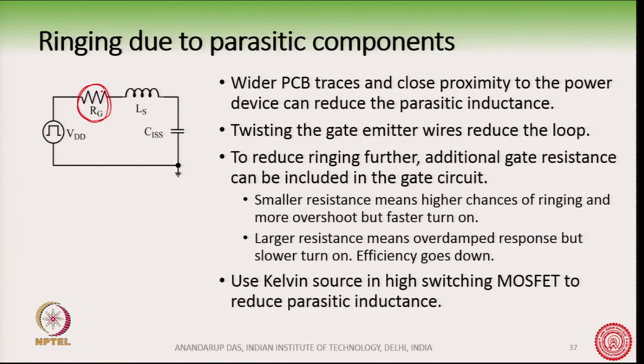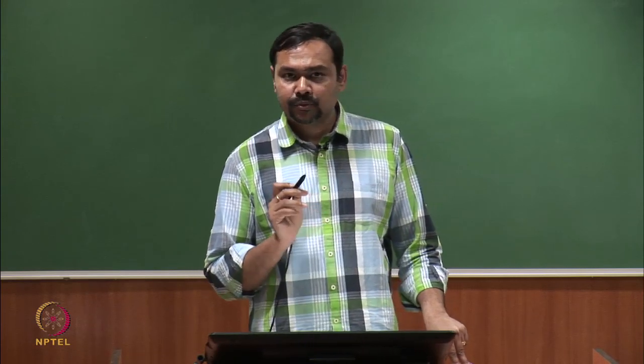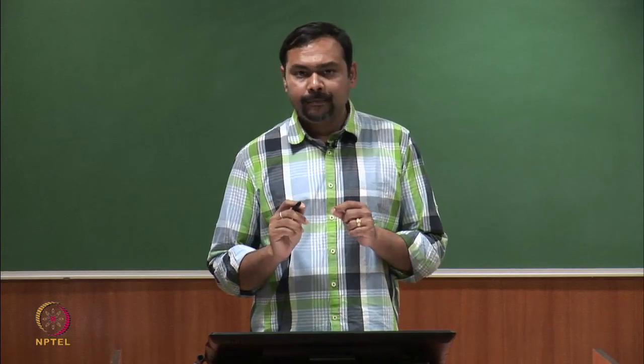Smaller resistance means higher chances of ringing and more overshoot, but faster turn on, whereas larger gate resistance means overdamped response, but slower turn on and more losses.